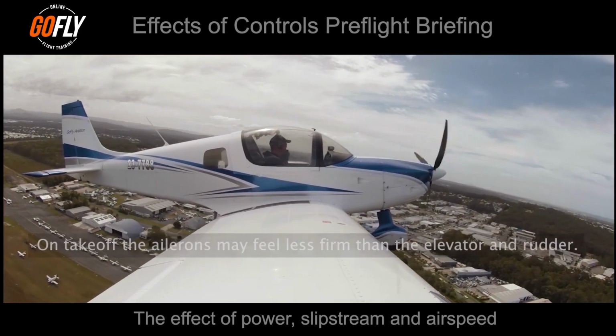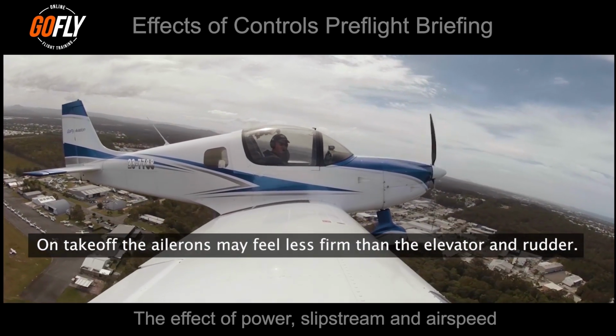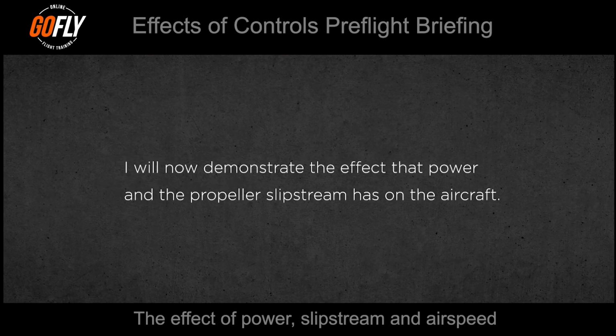So in this example on takeoff, the rudder and elevator could feel firm and responsive, and the ailerons feel less firm or sloppy. So in summary, in relation to the effect that airspeed has on the aircraft, at higher airspeeds, the controls feel more firm and more responsive, and at lower airspeeds, the controls feel less firm and less responsive or sloppy. I will now demonstrate the effect that power and the propeller slipstream has on the aircraft.